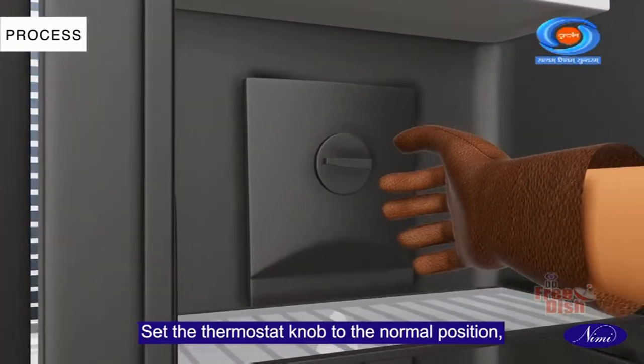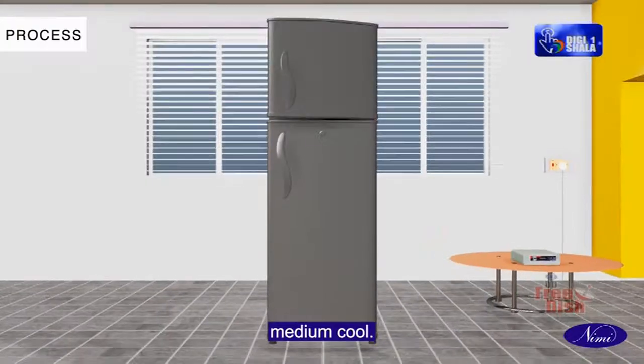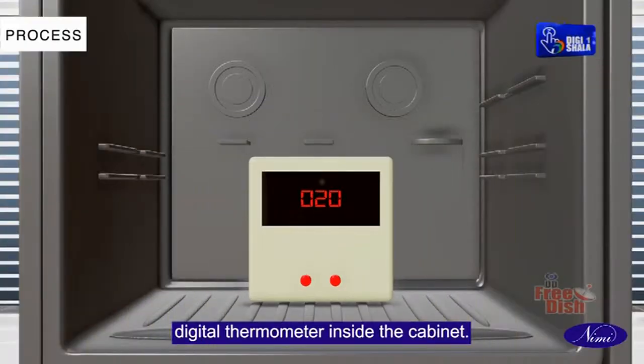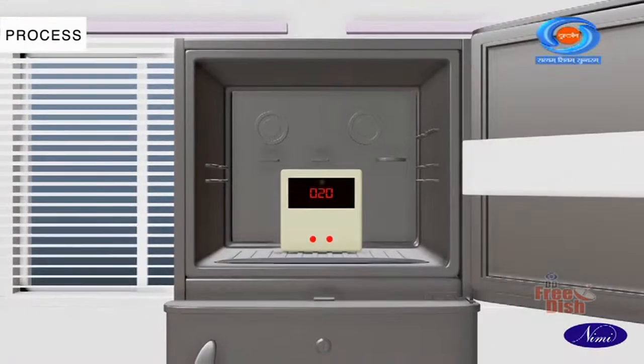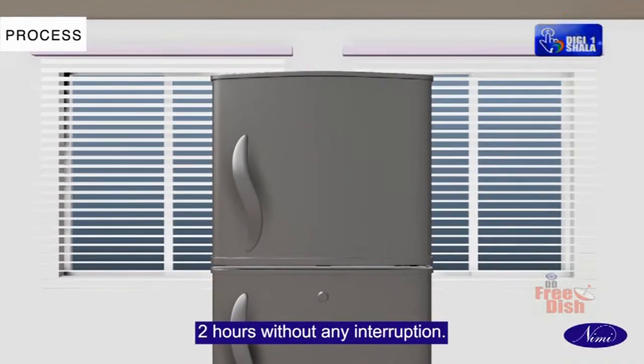Set the thermostat knob to the normal position, medium cool. Place the sensing probe of a digital thermometer inside the cabinet. Let the unit run continuously for 2 hours without any interruption.